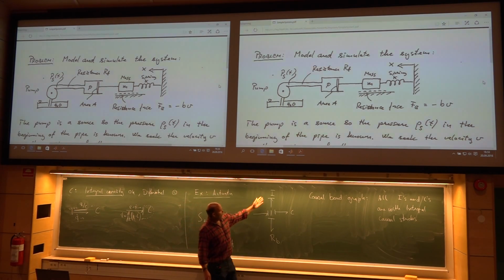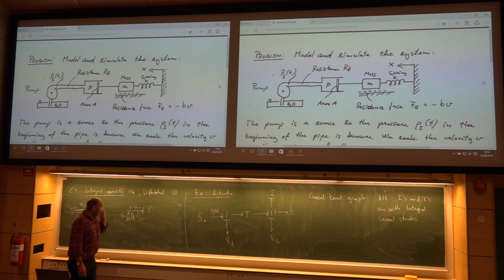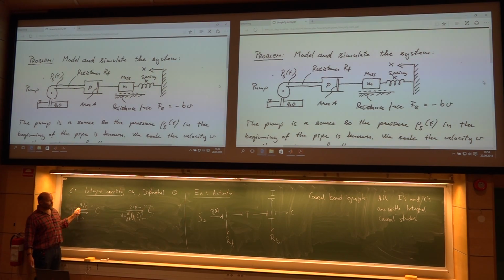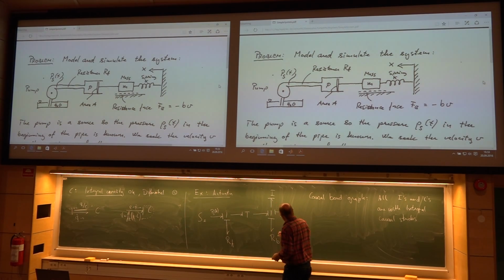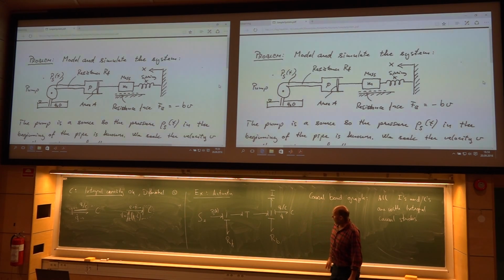When I have these energy storage elements on the correct integral form, then immediately you can use sort of the definition. So here you will have a q dot for this C element, a q dot here, and on top the effort will be Q divided by C. Here you should write a circle around this Q dot, just to inform you that this is on integral form. This is going to result in one differential equation. Same goes with the I element.